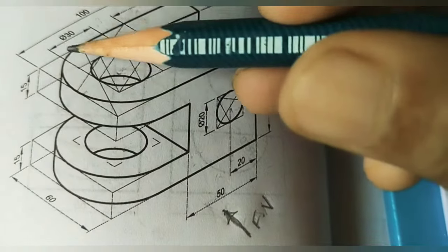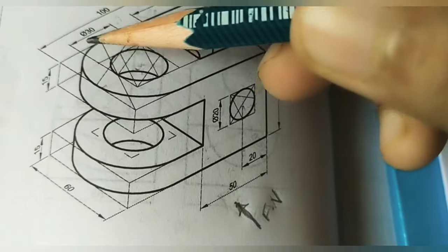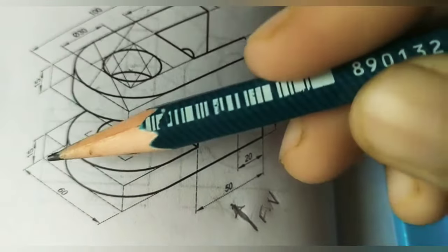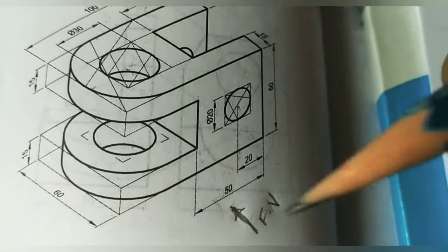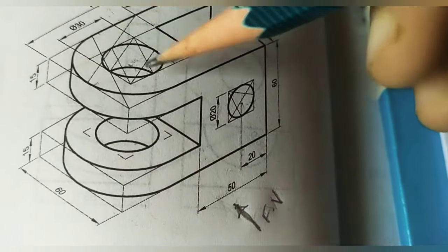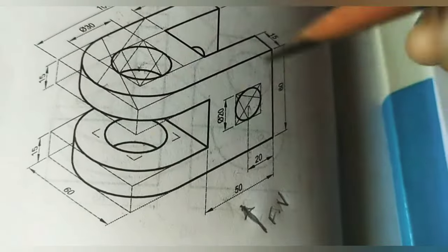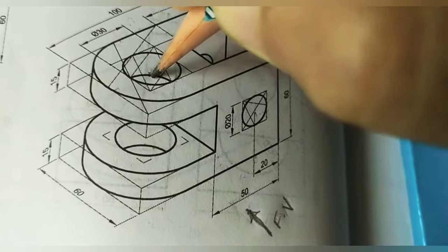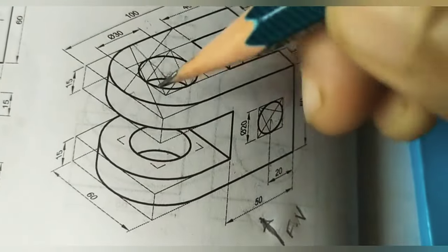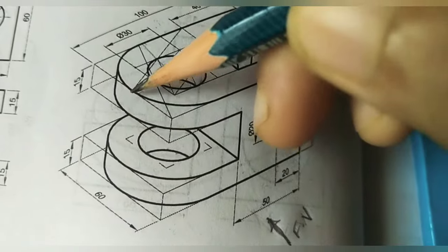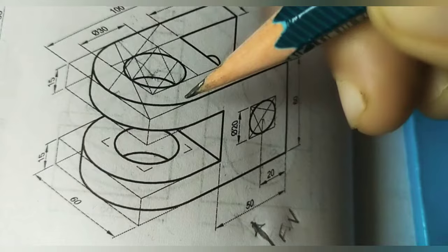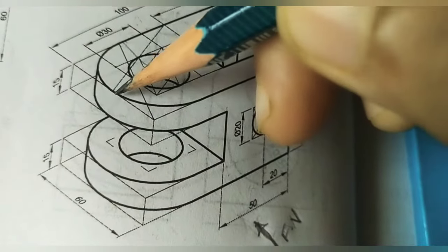If you are taking this circular one here, how much is it? This diameter is nothing but the width of this box. How much is it? 60 mm. Okay, so in 60 mm this is a semicircle diameter. Where is the center? It is half of the 60 mm. It is 30 mm. Okay, this distance, if we do roughly here, is 30 mm. Okay, total is 60 mm. This is 30 mm. Here the radius is 30 mm. Here also the radius is 30 mm for the bigger one. Wherever we can see, the radius will be the same. So here 30 means here also it is 30.